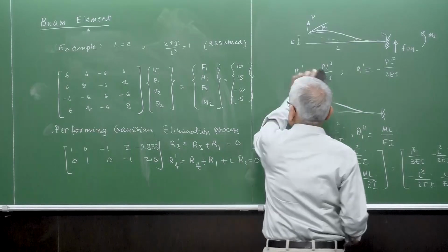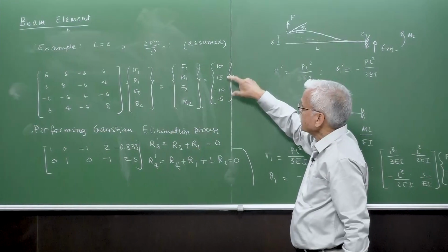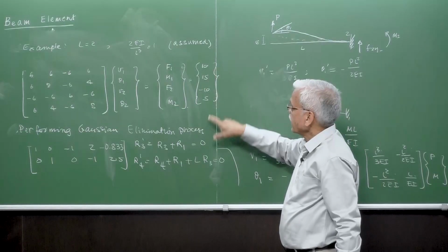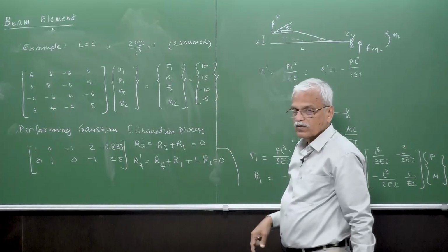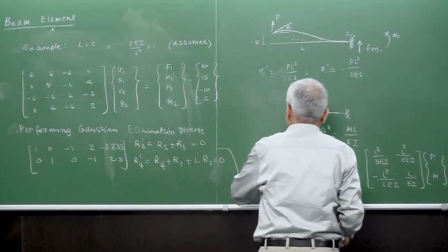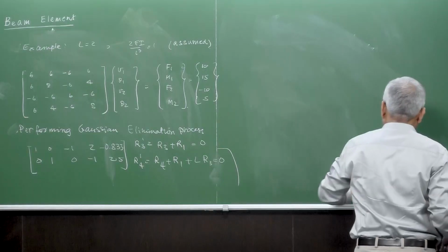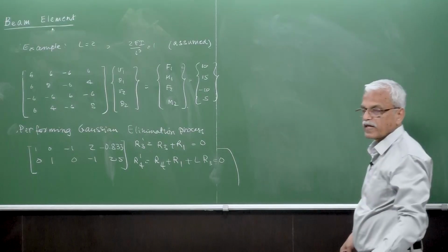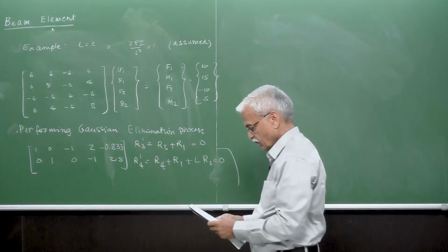Okay. So in fact, you can see that's what we have applied here. This force which we are applying here is opposite to this one. Together with these moments and the forces, we are able to get the moment equilibrium also. So we have two equilibrium equations satisfied, and that means that we have two rigid body modes.